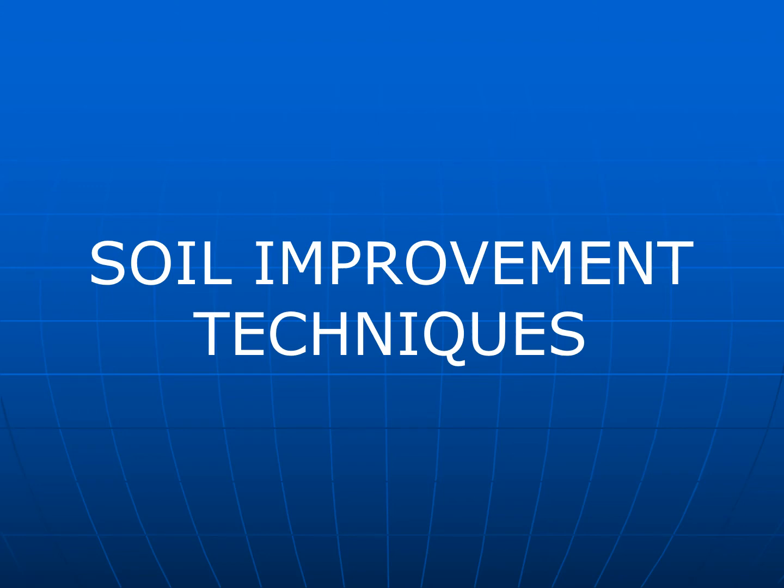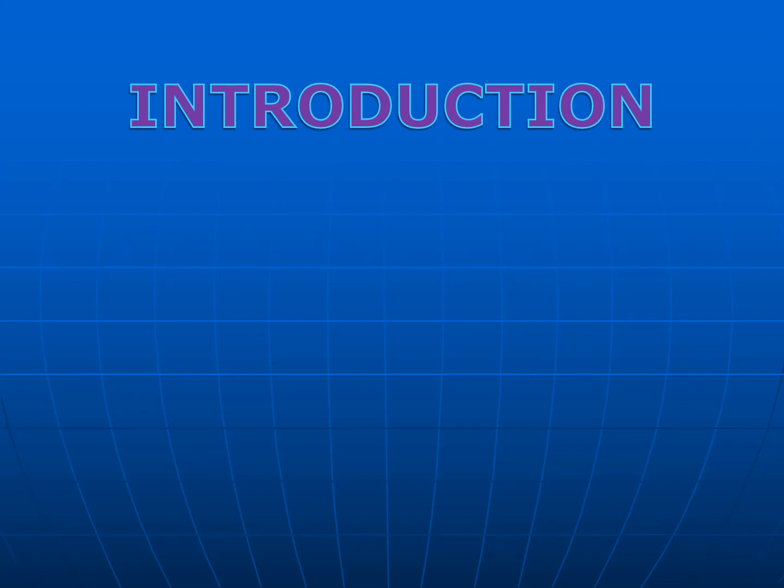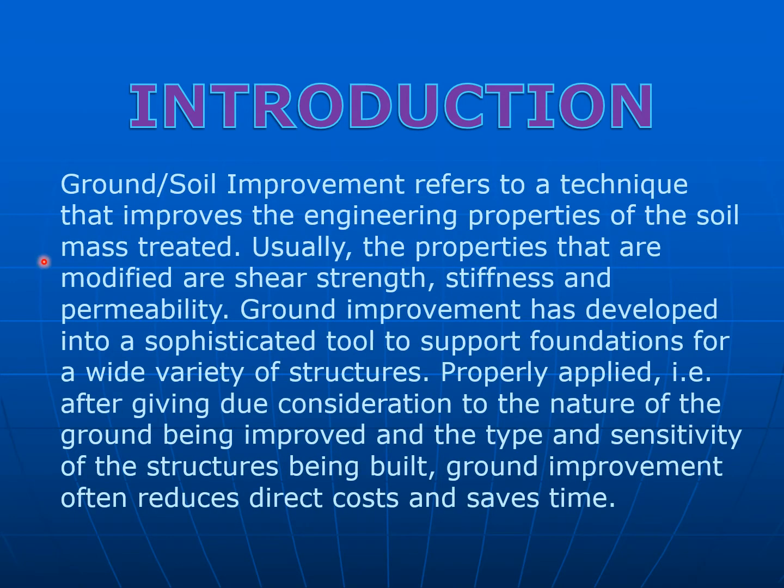The title of the subject is Soil Improvement Techniques. Ground or soil improvement refers to a technique that improves the engineering properties of the soil mass treated. Usually the properties that are modified are shear strength, stiffness and permeability. So three important properties: shear strength, stiffness and permeability.